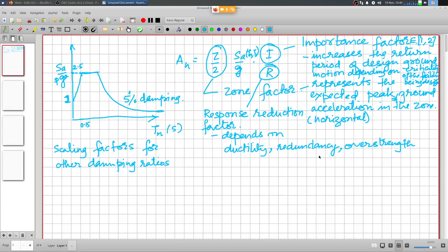It is for earthquake resistant design, we are going for doubly reinforced beams anyway, because it is going to be reversible in nature. So there is no single reinforced section in case of earthquake resistant design. So it is anyway over reinforced.